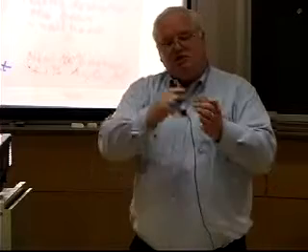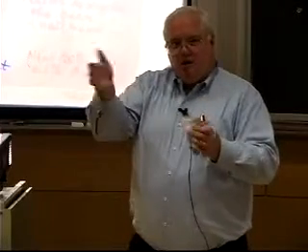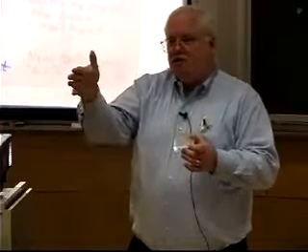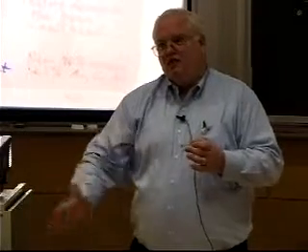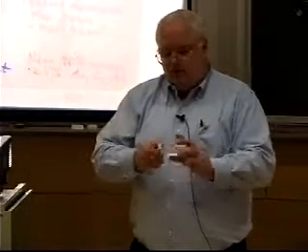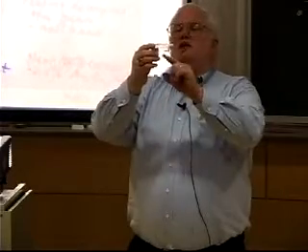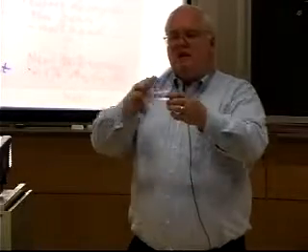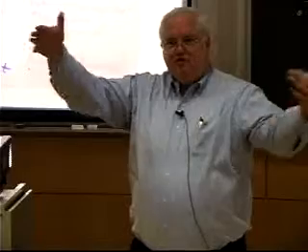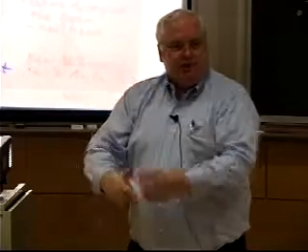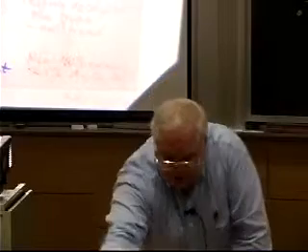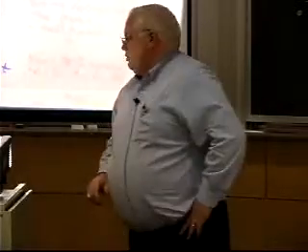And this one, which is much deeper, all they did was take that circle with the mirror and tilt it to turn it into a sharp ellipse, to turn it into a line scan so you could heat treat with that laser. So this one, if you turn it upside down, is not very deep. This one is much deeper, but all they did is tilt the mirror, and if you bring a circle in this way against the mirror at an angle, it projects an ellipse. So all they did was project an ellipse to create a line source. As we say in laser technology, it's all done with mirrors, right?